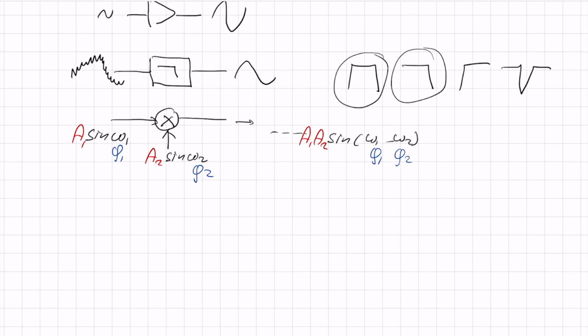So this is something interesting, because I can take a high frequency signal that I want to receive, which may have amplitude modulation or phase modulation or both. I multiply that with a clean sine wave that I make myself with a fixed amplitude and a fixed phase, and they're very clean, very stable.